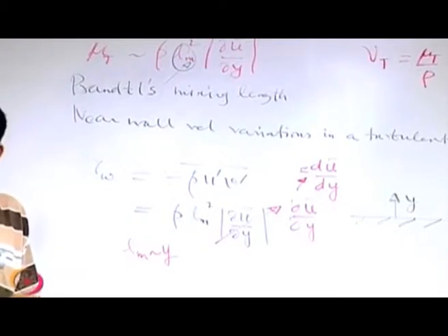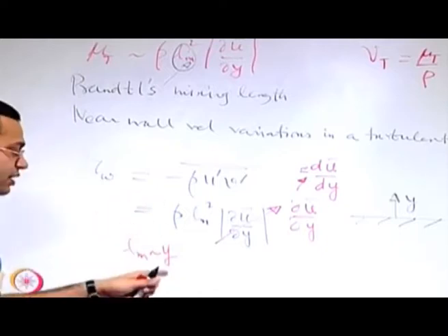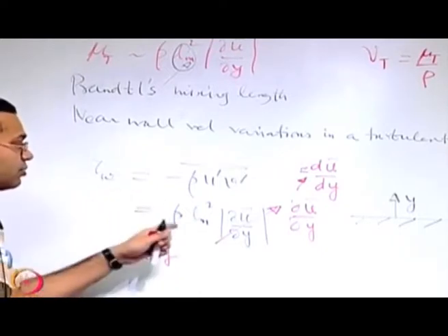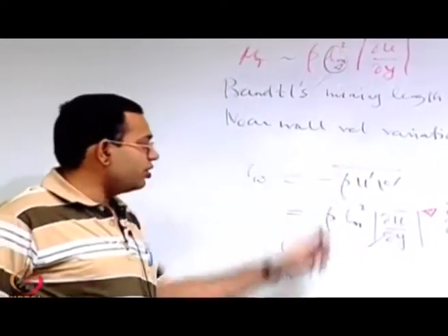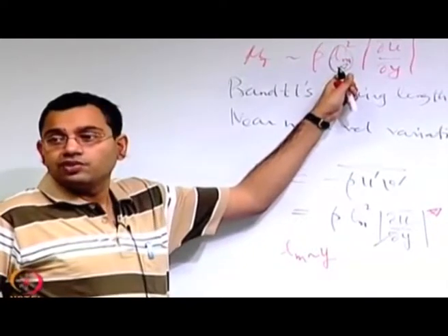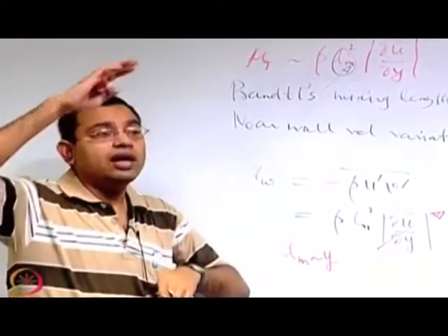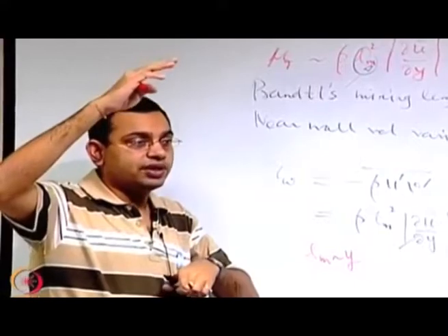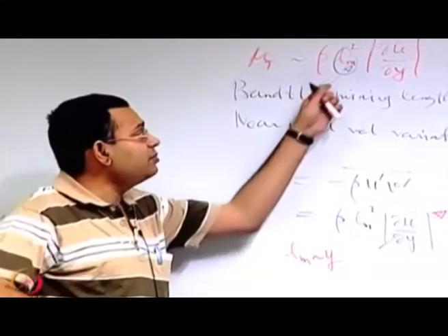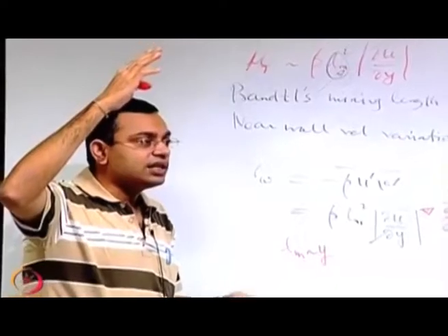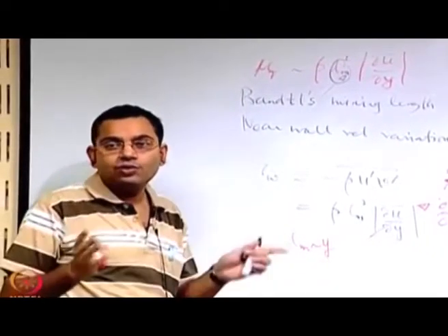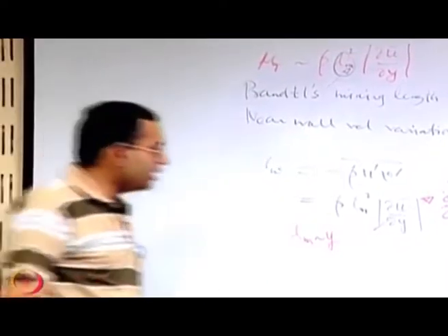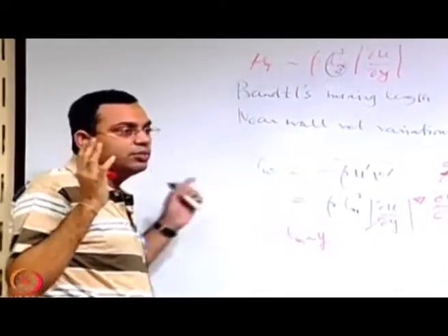At the wall the laminar effect is there, that which solely dictates the factor. So at the wall whatever is the turbulent stress, that has to be 0, right, and so when y equal to 0 this becomes 0. As you go more and more away from the wall, it has to be more and more important. So physically this term will be increasing as y is increasing, and a simple increasing law may be a linear law. That is what was the logic of Prandtl, and accordingly see these type of logical thoughts are important, because